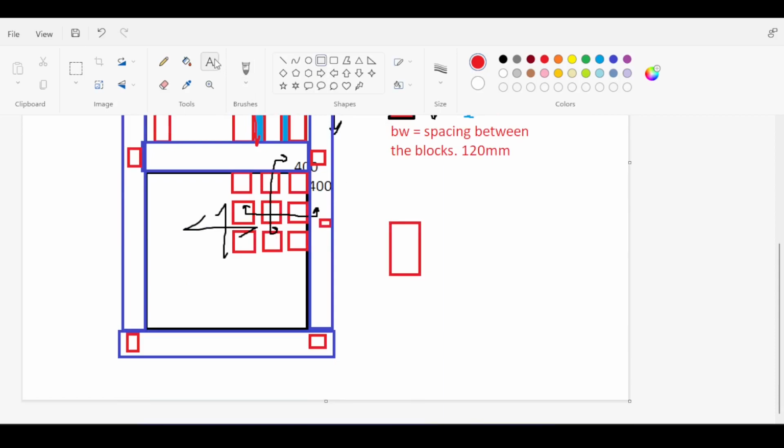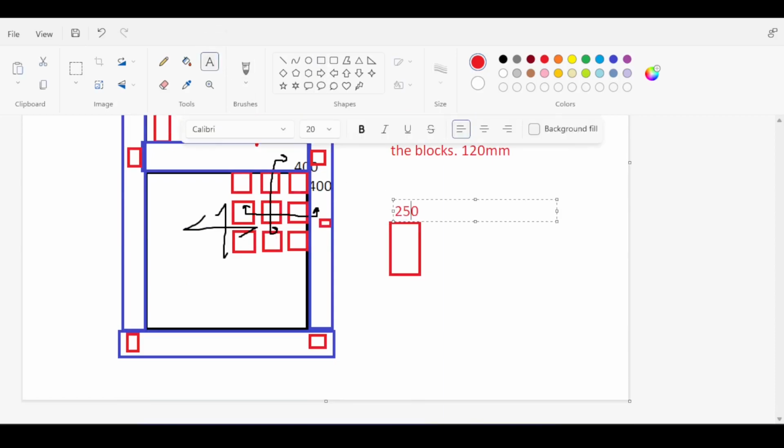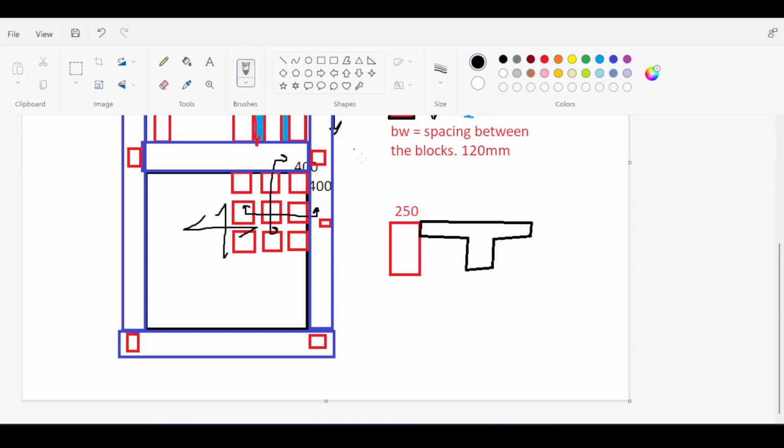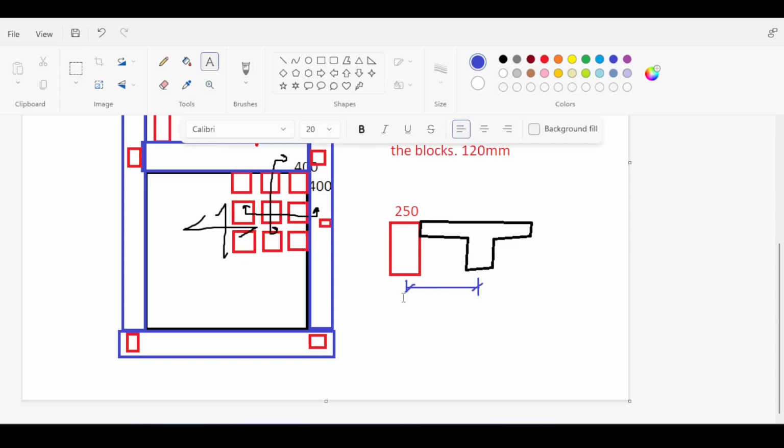The beam had a dimension of 250, and I want to connect a rib to it. And the question is, what's the center spacing of the first rib? Because this is like one of the issues you need to take care of. Now, to be honest, if you mess up the first spacing, it will not be like a big difference, but why not be accurate? So the first spacing is going to be basically 250 plus 520, all of that divided by 2, between two brackets here. So this plus this in brackets divided by 2.